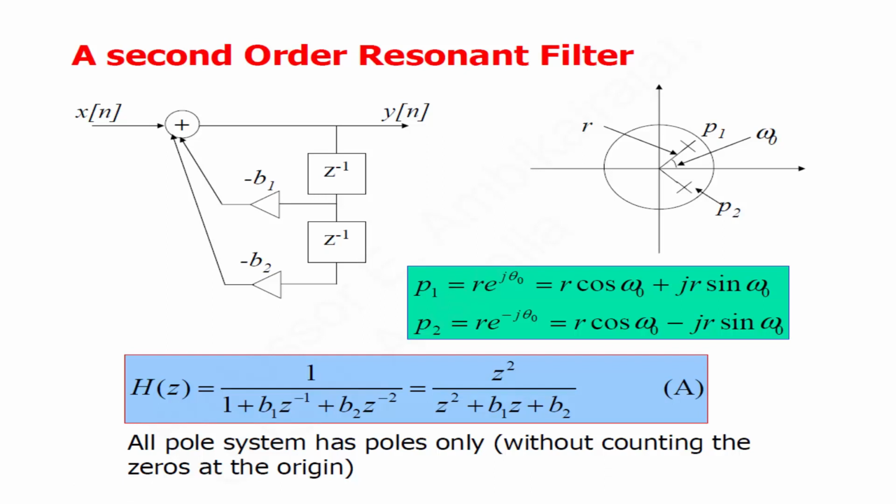You will not be able to obtain the resonance taking place. The magnitude curve will not peak upwards. If it will not peak upwards, you will not be able to achieve a band pass filter.